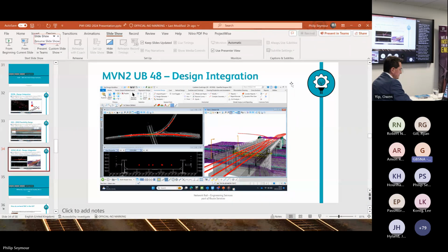Next slide, please. And then as part of a peer review or a CAP3 check, I was asked to look at integrating a recent ESDD multidisciplinary design for bridge reconstruction across the M62. And this was a chance to bring in the 3D model from civils, look at the earthworks, look at the track alignments, and then produce cross sections, which were really powerful, being able to check the tracks were coplanar, sufficient ballast depths, and clearances to underlying structures. So again, it's trying to give you an insight into how you can start using 3D designs for integration and not having to look at bits of paper, reports, transposition of numbers, typos. It gives you full confidence in 3D.